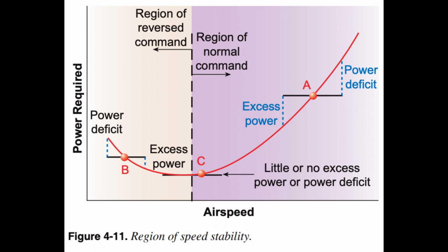Acceleration in cruise flight. Aircraft accelerate in level flight because of an excess of power over what is required to maintain a steady speed. This is the same excess power used to climb. Upon reaching the desired altitude with pitch being lowered to maintain that altitude, the excess power now accelerates the aircraft to its cruise speed. However, reducing power too soon after level off results in a longer period of time to accelerate.